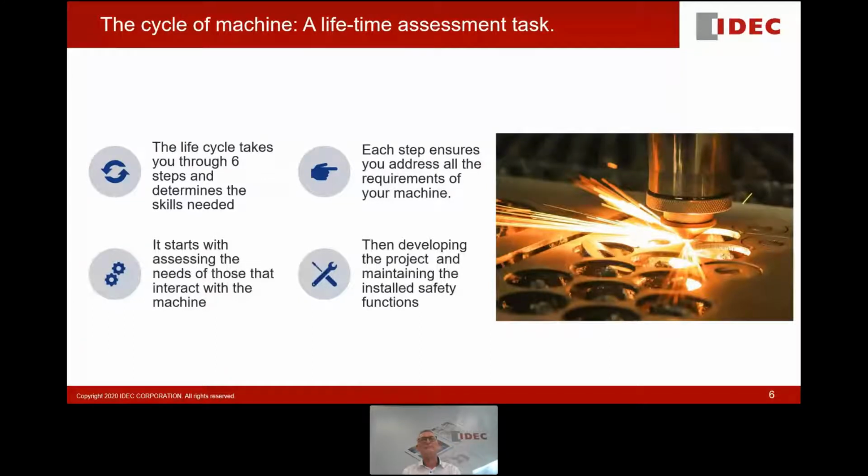It's a common myth that safety devices fail safe. Well, that's actually not true. Safety devices do fail safe, but they are not indestructible. And if you hit them hard enough and long enough, they may fail in an unpredictable manner. So you have to maintain safety functions and check that they are performing their function properly and that they will continue to do so.